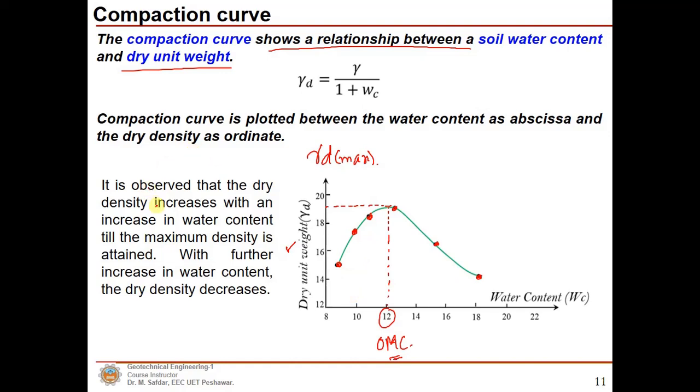It is observed that the dry density increases with the increase in the water content till the maximum density is attained. With further increase in the water content, the dry density decreases, as discussed in our previous slide.